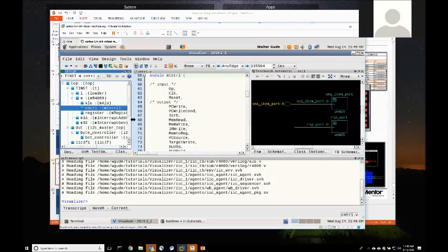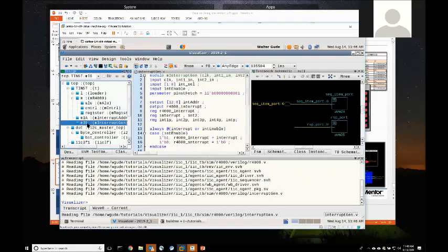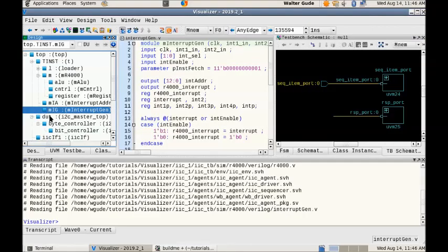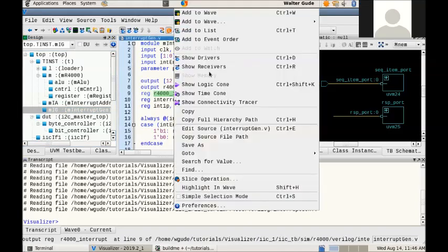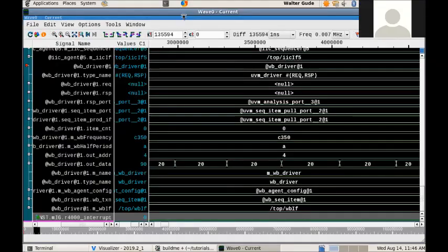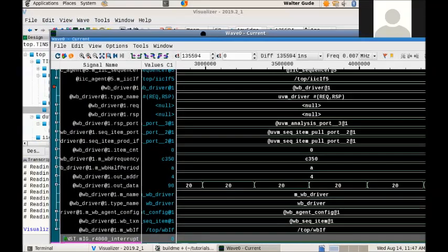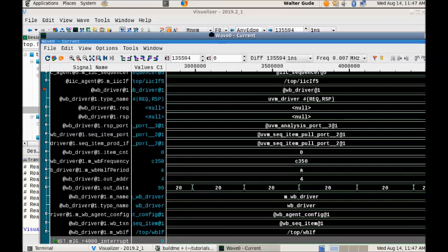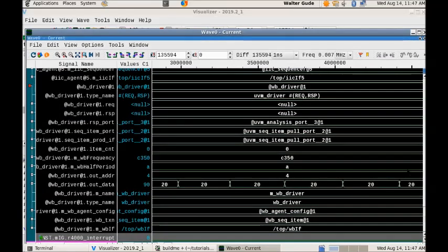While you're doing that, Walter, one thing to remember is that this is a post-sim. As Walter mentioned, when you run the simulation, you set up your switches to generate these files that can be used by Visualizer later. The advantage is that when you're in this debugging mode, you can traverse the whole waveform very quickly, versus the original way where you take up a license for the simulator to use the viewing window. That's one huge advantage. But the methodology would have to be done in a post-sim environment.